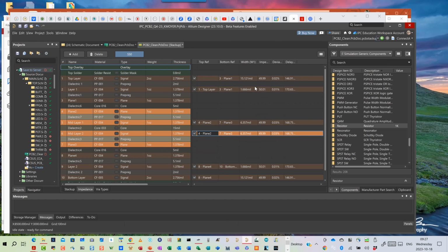So aside from this one, which we aren't actually going to allow any digital routing on this special layer right here, we're going to escape route from there and do all of our digital routing on these 2 layers right here. I don't care that this one is showing underneath. Remember, we just saw that manufacturability thing that says for this 1 ounce copper for etching, my trace width minimum must be 5 mils. So I'm looking and saying, yep, 15 mils there, 6 mils there, I'm fine. I am well within my specified range of allowed widths for manufacturability as well as characteristic impedance. So I've now defined my 50 ohm profile right here.